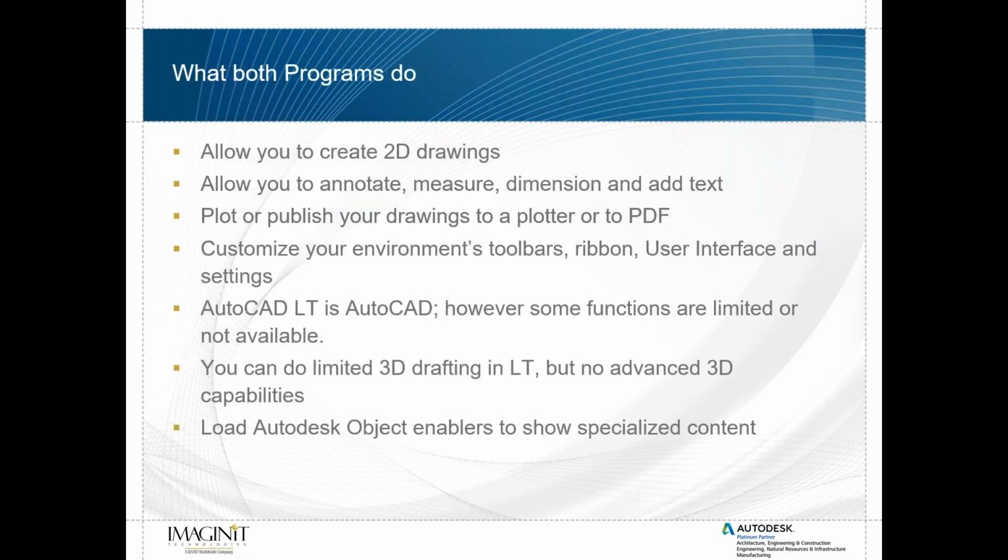So what both programs do really well, they allow you to create 2D drawings. Both programs are phenomenally good at creating 2D drawings. They allow you to annotate, measure, dimension, add text, plot or publish your drawings to a plotter or PDF. You can customize your environment's toolbars, ribbon, user interface, and settings. You know, the big thing is AutoCAD LT is still AutoCAD. Some functions are limited or simply not available. And you can do some limited 3D drafting in AutoCAD LT, but no advanced 3D capabilities.